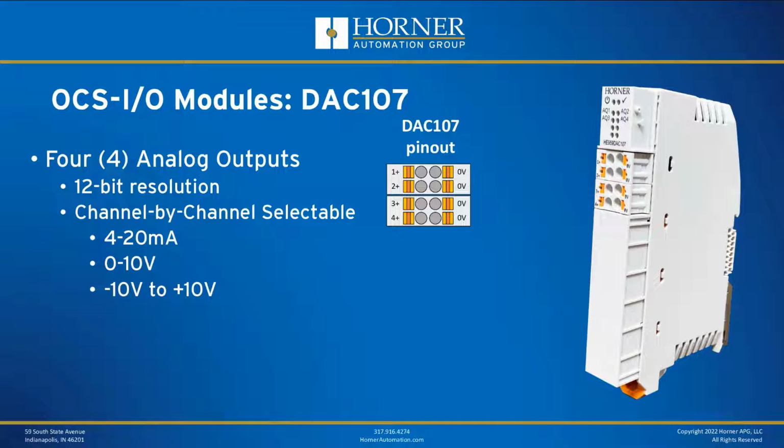And then on the analog output side, we have a 4-channel module as well, selectable between 4 to 20 milliamps and 0 to 10 volts. And we also include support for -10 to +10, which is still in pretty heavy use for applications involving motion, because you do end up with plenty of signals on both ends of the spectrum there. So it's nice that that's supported with a single module.